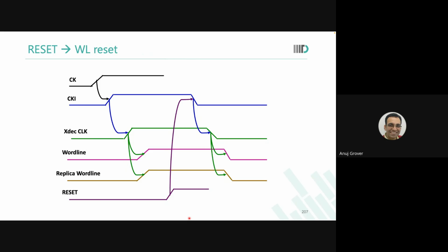And that is determined by how you have designed the reset signal, how much margin you have left in your replica path. Are you getting it? So you want the replica path to be safe, but you cannot have too much margin left there. Otherwise, performance will go for a toss. Are you getting it?